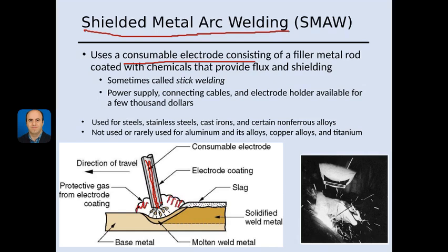So this gas is provided by melting this flux. That gas is going to protect the weld pool from mixing with the air contamination, because when the metal is hot, it is ready to be oxidized. So we want to protect it from the air contamination.